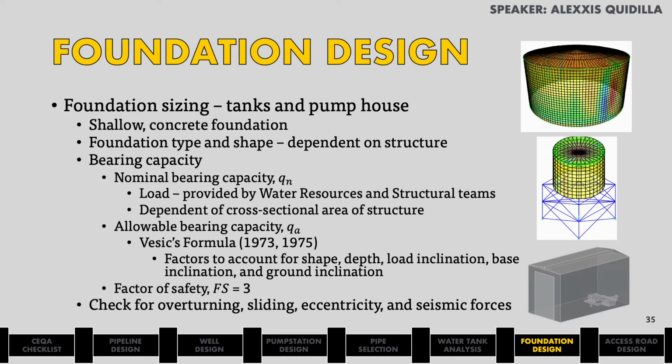The foundation type and shape is different for each of the 3 structures to cater to their specific loads, shapes, and supplemental structures. Using information from the boring logs, the geotechnical team was able to calculate the bearing capacity, which is the capacity of the soil to support loads applied to the ground. The nominal bearing capacity of each structure is dependent on its load, which was provided by our water resources and structural teams. The allowable bearing capacity was calculated using Vesic's formula, which contains factors that account for shape, depth, and